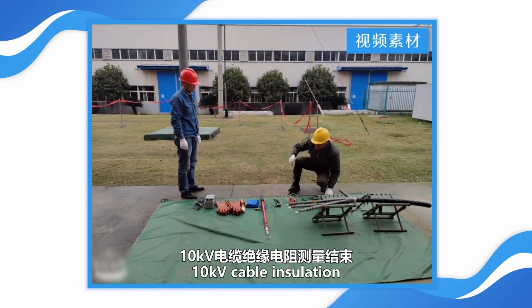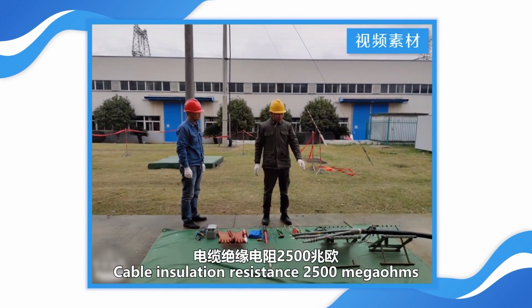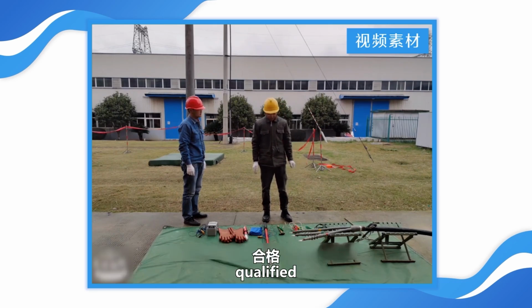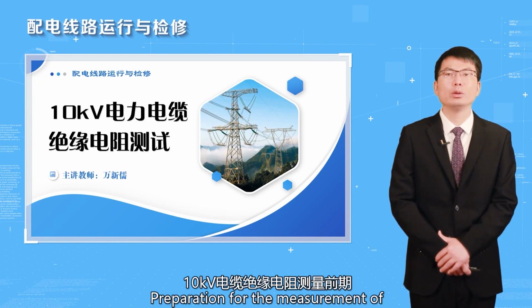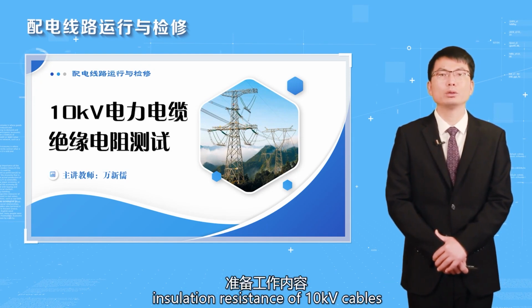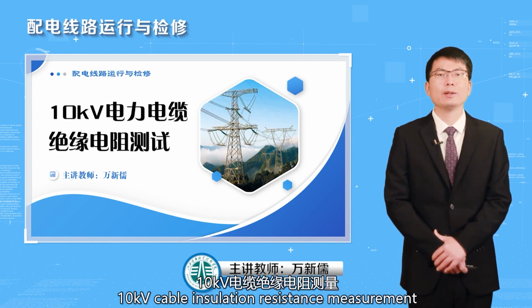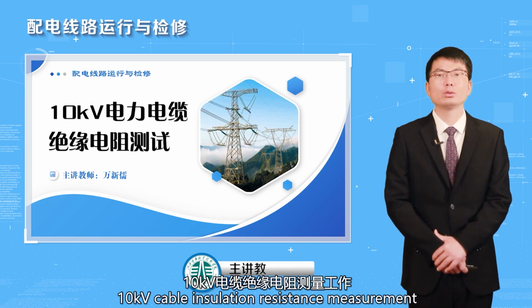Ten kilovolt cable insulation resistance measurement completed. Cable insulation resistance 2500 megohms: qualified. This lesson focuses on preparation for the measurement of insulation resistance of 10 kV cables and the main points of the measurement process.